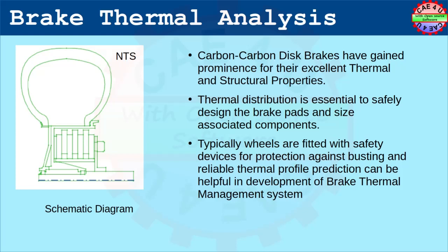So, carbon-carbon disc brakes have gained significant prominence because of their excellent thermal and structural properties. Though the application is more specific to aircraft, the general principle can be derived for any similar applications. Owing to the complexity of the material properties, that is the orthotropic characteristic of composite material, it is important to calculate the temperature distribution so that the brake pads and the associated components can be designed within their safety limits.